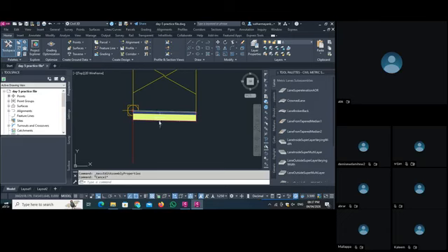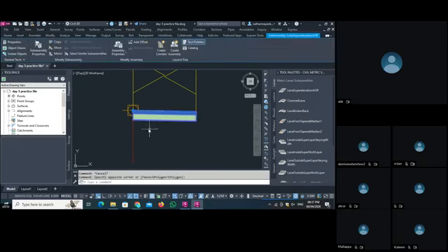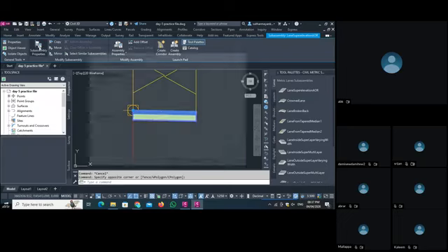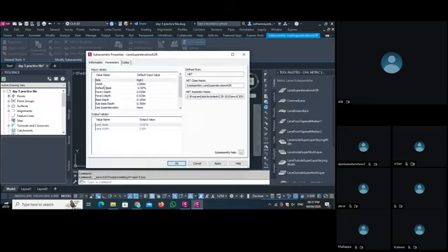See, once we provide this lane, remember, as we click on the sub assembly property, in the parameter we change our width to 3 meters, and our slope is -2%. So we have to remember these two things. Throughout the work we use these two values. For betterment, because every time Civil 3D gives different property values, we set it this way to make our flow better.